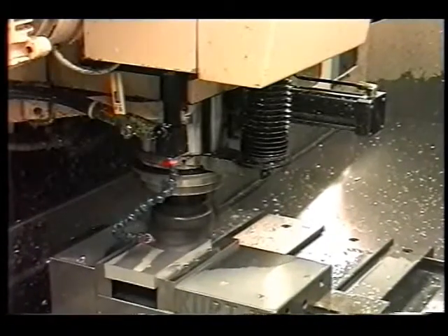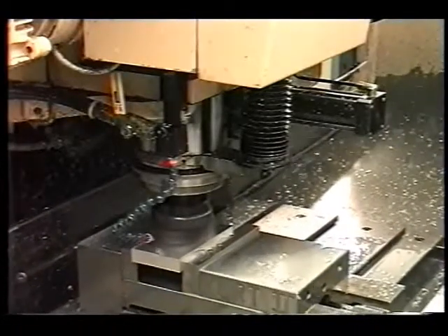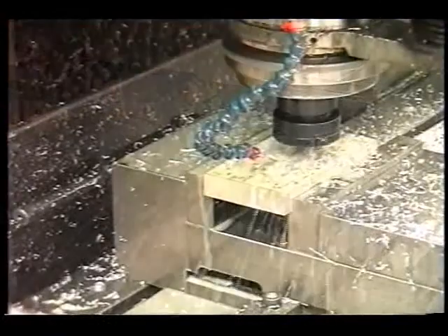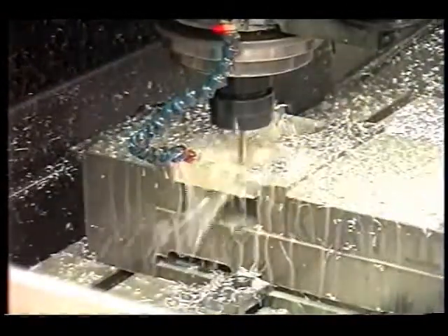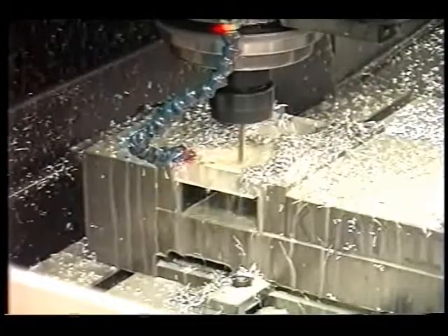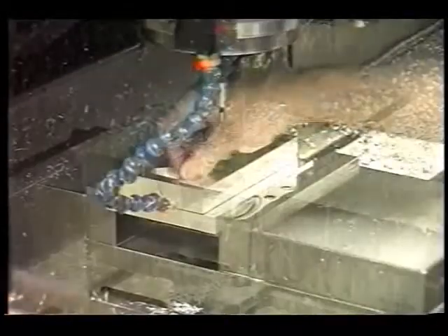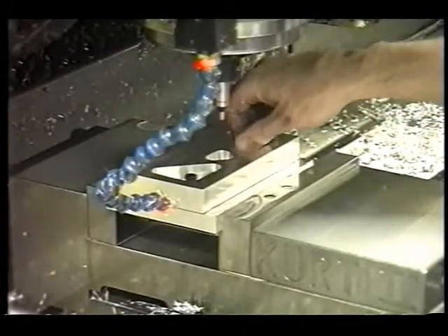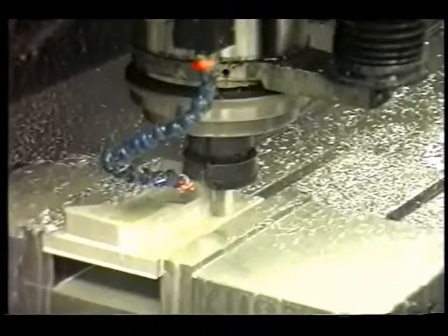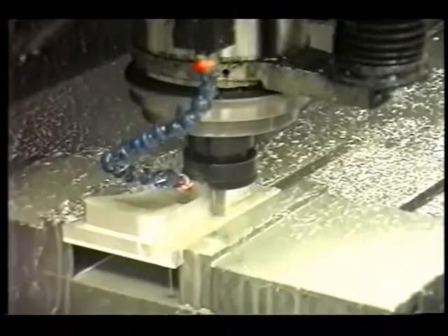The 4-step manufacturing process starts by planing the stock of metal to the approximate dimensions. Then, interior details are milled out, followed by drilling holes for a fixture plate to support later operations. The fixture plate is then attached, and finally, the outer profile of the part is cut now that it won't interfere with the vise.